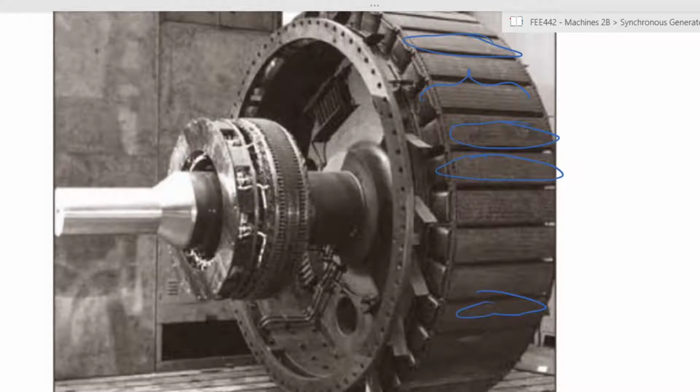And what you see here now, this is the exciter, that is the field windings that are supplied to the machine. Straight away you notice that the windings themselves are very small compared to the rest of the machine. So what you're doing is you're supplying a small current or a small field, and it is able to generate a larger field.